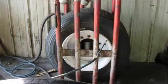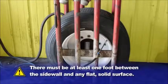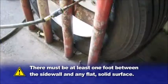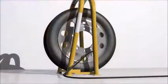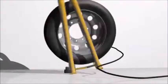Here is an example of the correct location because the restraining device appears to be out of the traffic and work areas, but in the wrong position because the sidewall of the tire is within 1 foot of the wall. And to make matters worse, the device has been bolted to the floor, so the bolts can become shrapnel if the metal wall doesn't collapse first.